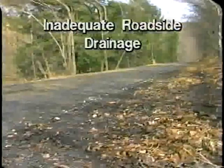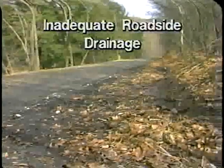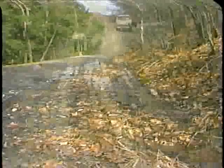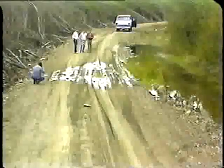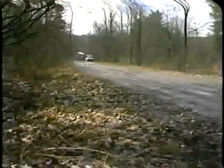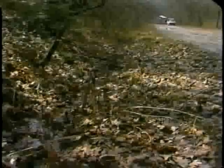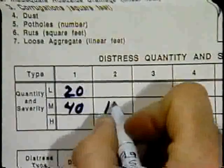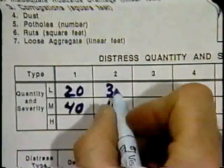Next, we look at inadequate roadside drainage. When ditches and culverts fail to carry runoff, pools form alongside the road. The presence of these pools can weaken the road, or they may drain across the road carrying surface material away. Look for ponding of water or evidence of ponding water, and also for overgrowth or debris in the ditches. Again, you need to record the length of the problem in feet. This sample unit has 15 feet of medium severity, and beyond that, 30 feet of low severity. Refer to the field manual for help in judging severity level.